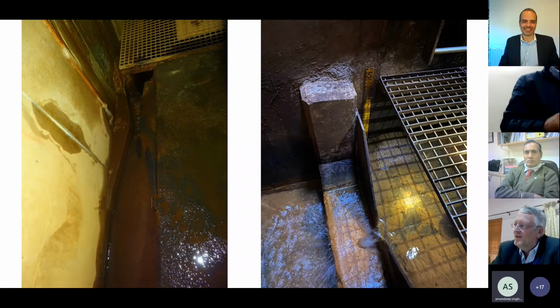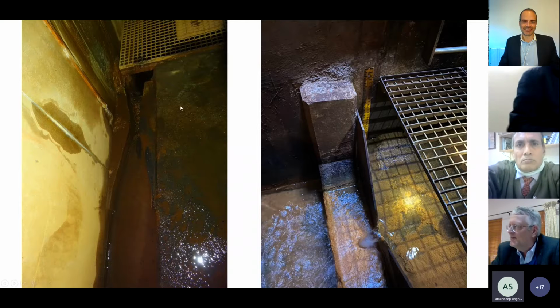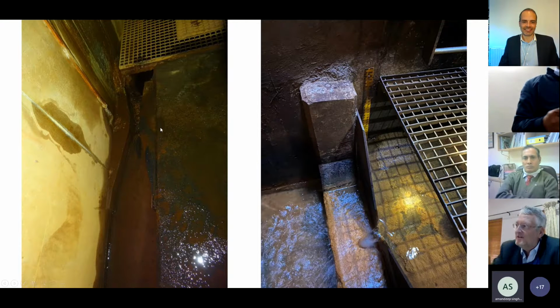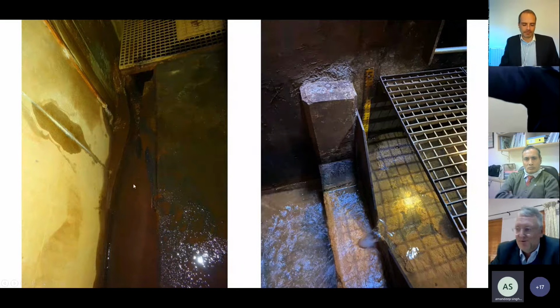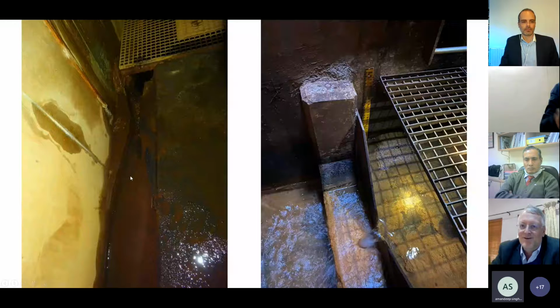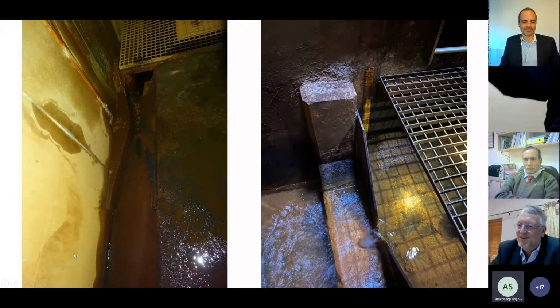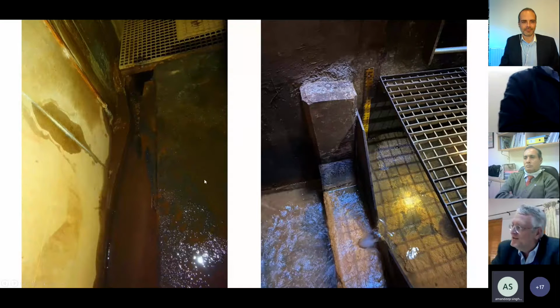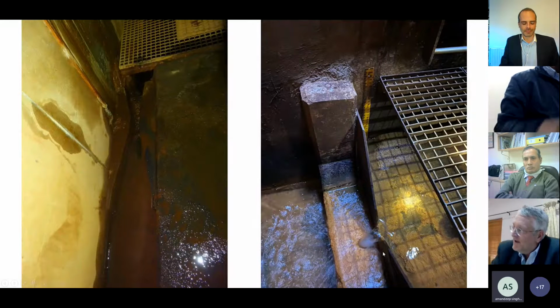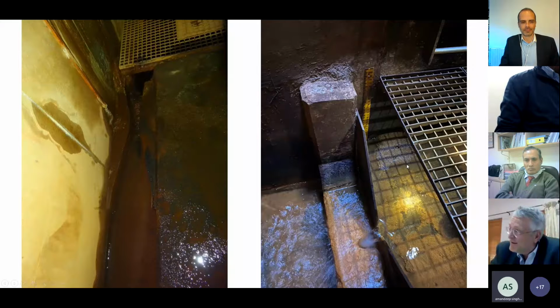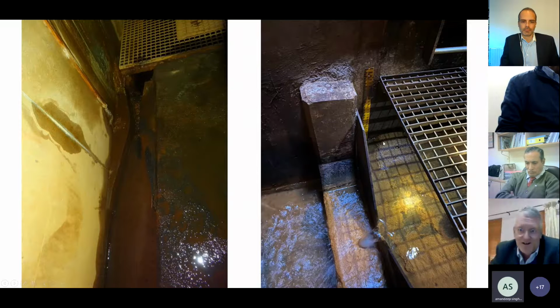Typically in our environment, this is the typical layout, and Manuel was talking about it. In my world, dam owners normally don't like automatic installations. They want to have manual ones. Here's an example, a V-notch. You can see the sediment that collected there, so you can imagine the flows that one actually determines. There's a permanent installation of the ruler where you read off, and it's full of sediment, so the readings that you get are just not correct.